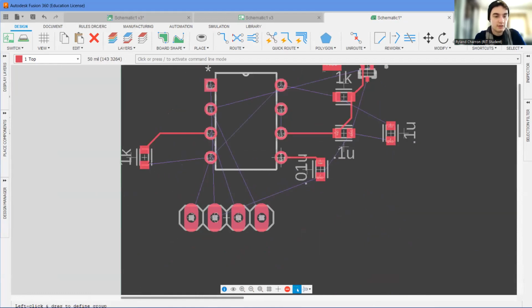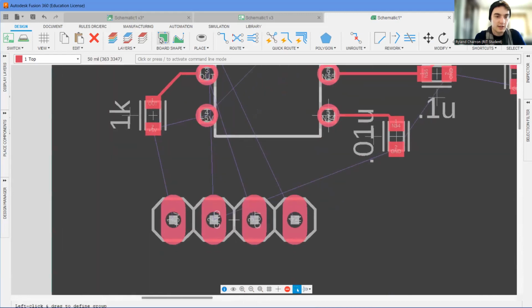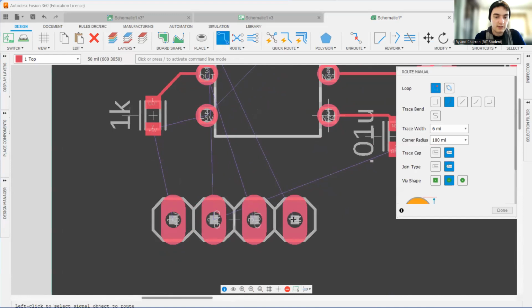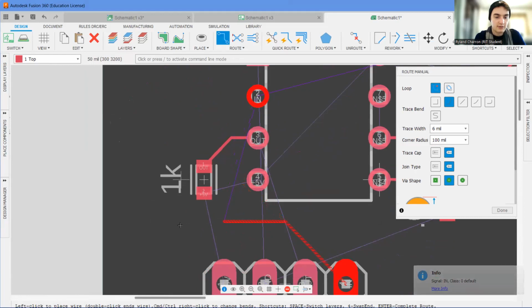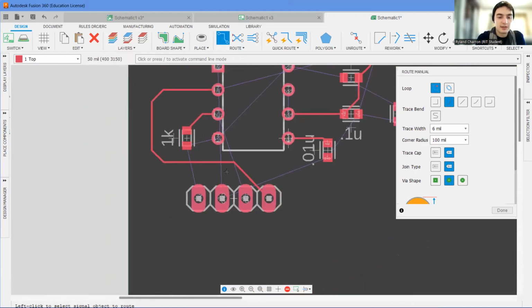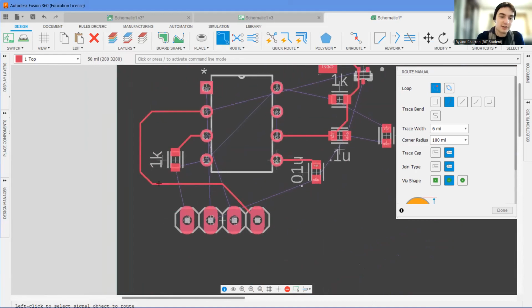If we move this guy, the wire will adjust with it. Come on. There we go. And now maybe we can take our input pin and trace it around. See, it doesn't like that. So we got to go around. And I just clicked it right here to tell it I want it to place there. And we're just going to bring that to the input. Now, I think you could probably see that this is an unnecessarily long wire. This is something you would want to try to minimize in your design.